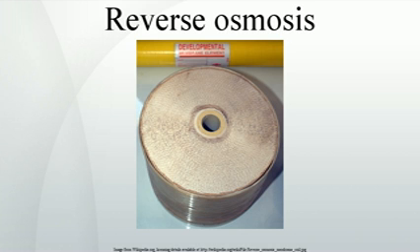Pressure exchanger, using the pressurized concentrate flow, in direct contact or via a piston, to pressurize part of the membrane feed flow to near concentrate flow pressure. A boost pump then raises this pressure by typically 3 bar/50 psi to the membrane feed pressure. This reduces flow needed from the high-pressure pump by an amount equal to the concentrate flow, typically 60%, and thereby its energy input. These are widely used on larger low-energy systems. They are capable of 3 kWh per meter cubed or less energy consumption.